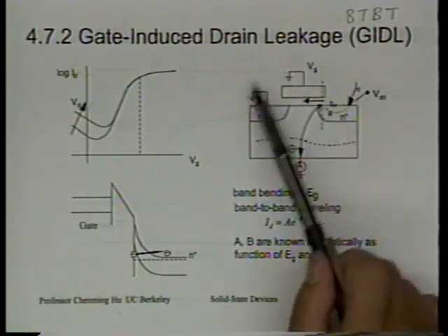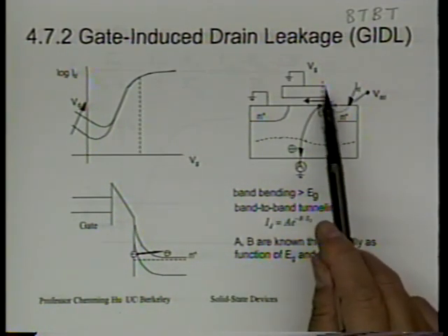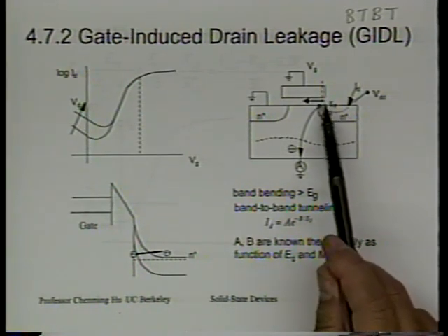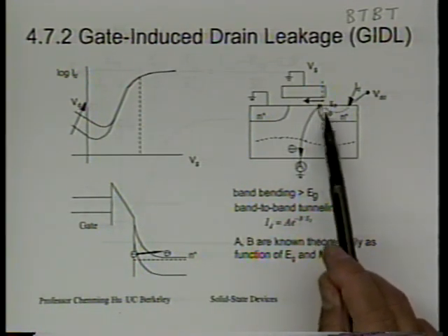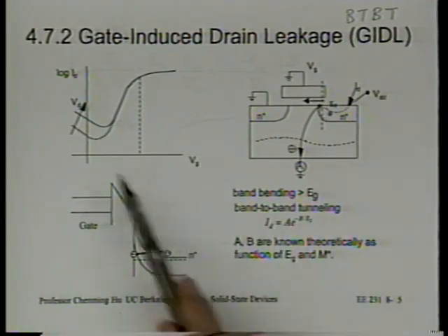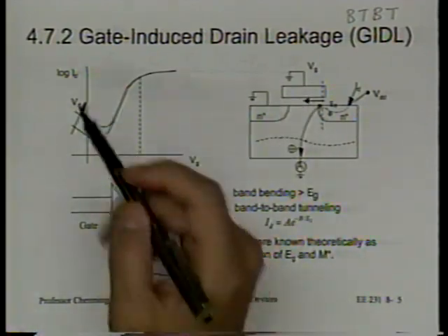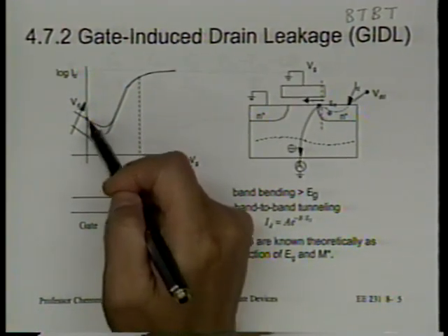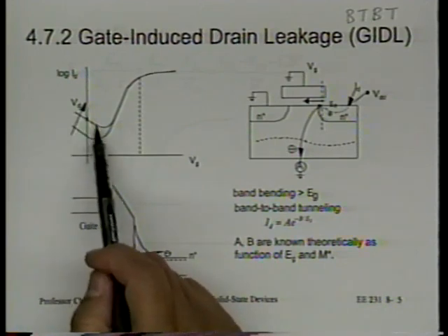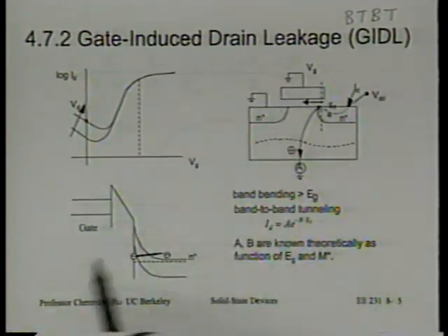So this is a cross-section of an MOS capacitor. I'm directing your attention to this portion where you see the gate electrode, you see the gate oxide, you see the drain diffusion region that we call N+ here. Okay? And let's remember, the bias under which we observe this current is Vg equal to 0. I'm particularly looking at one point here, right? Of course, this model will also apply for other VGs, but let's just assume Vg is equal to 0 right now. Just make it simple, all right?